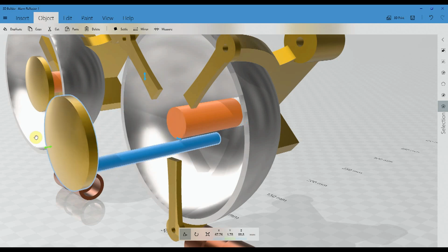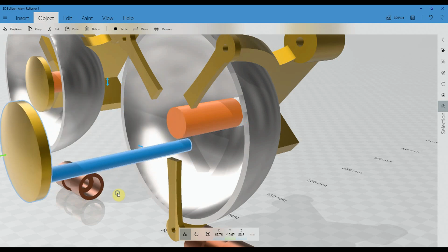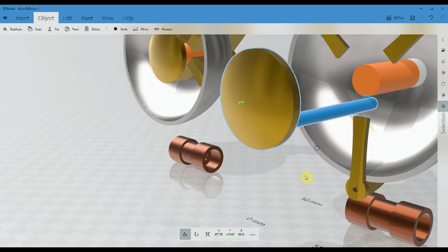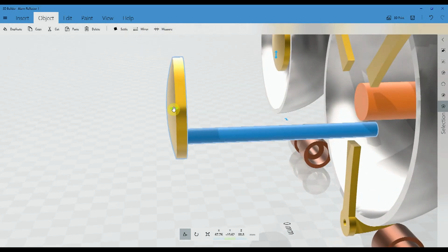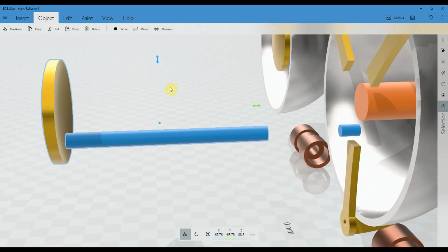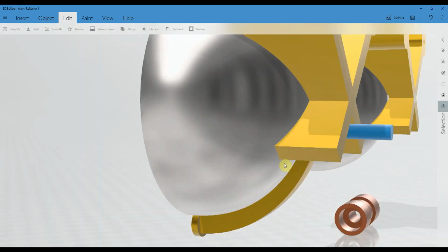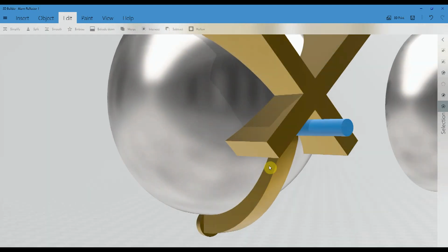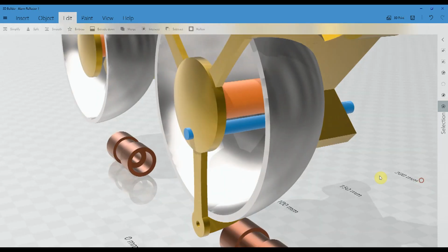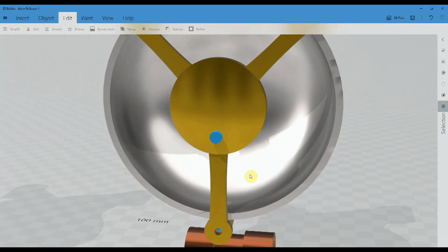Now I need to add a hole for the alarm set flickering LED indicator. So I'm going to use a brass rod tube at the back behind it to take the wires away, and I've made a little cylinder that's 5mm diameter, which is the size of a standard LED, which I will subtract later, but I'll leave that like that for now.